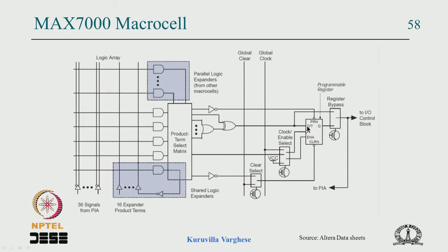and you can see there is a fuse which is a programmable register. That means depending on the value programmed here, it will become a D flip flop or a T flip flop. So you can imagine a simple circuit where by 1 or 0 you can switch between D and T, maybe you can think of such a circuit, it's very simple.